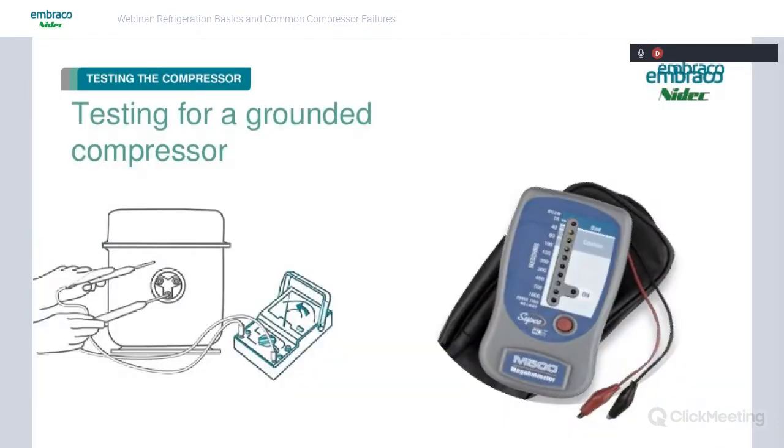So the second test, basically, we call it testing for a grounded compressor. What you're really doing is you're reading the condition of the insulation around the windings. A lot of people like to use their multimeter for this, but it's not recommended. It's recommended to use a megohm meter.